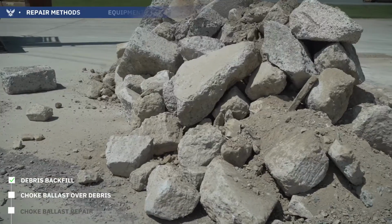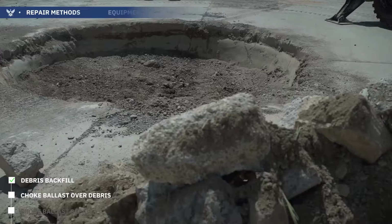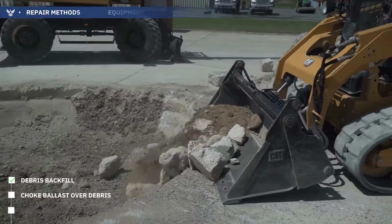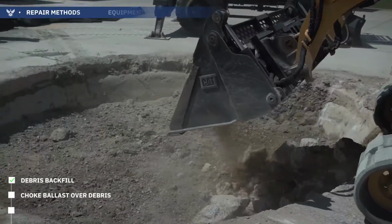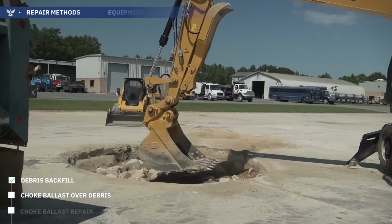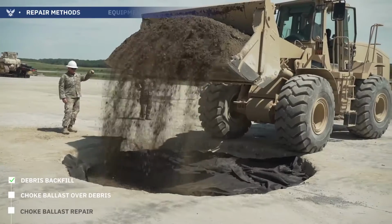Choke ballast over debris crater. Used when subsurface debris is suitable for fill but limited. Fill the crater with usable debris. Continue to fill the crater up to 18 inches below the surface with ballast rock and fill the remaining portion of the crater with crushed stone.